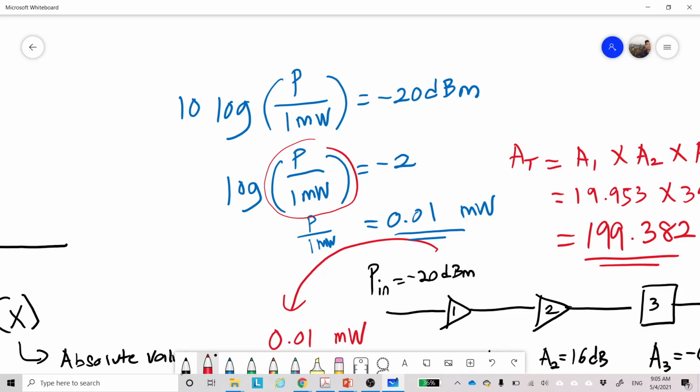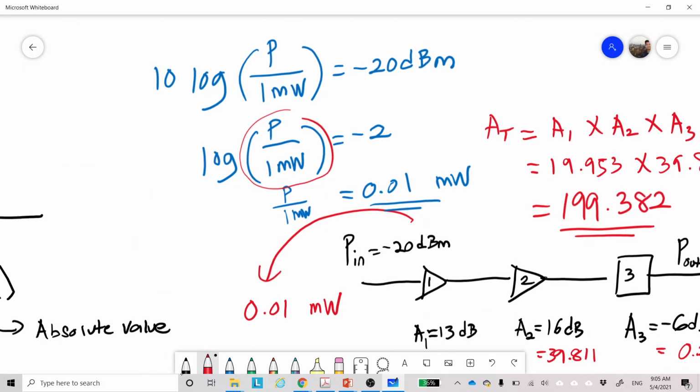So that's why when we do direct conversions of anti-log for the dBm, we will get it in terms of milliwatt. Okay, if we do direct conversions of anti-log for the dB micro, we will get the value in terms of microwatt. Okay, if we do direct conversions of dBW, we will get the value in watt.